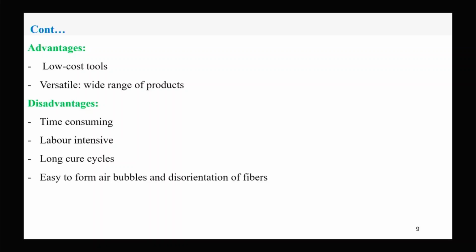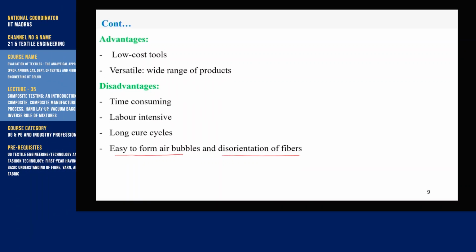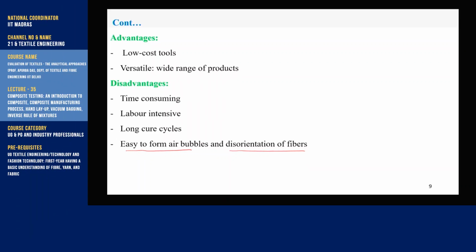Here the main disadvantage is that it is easy to form air bubbles. So here void content may be high, and also during handling, disorientation of fibers may be there. Whatever random alignment was there initially, the fiber may get disoriented, and there is a possibility of thickness variation also.